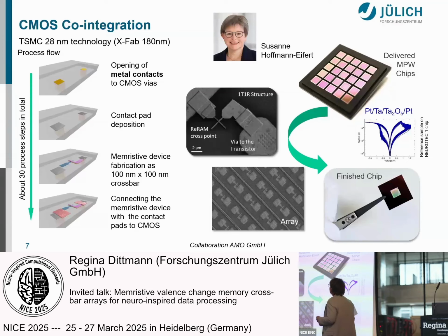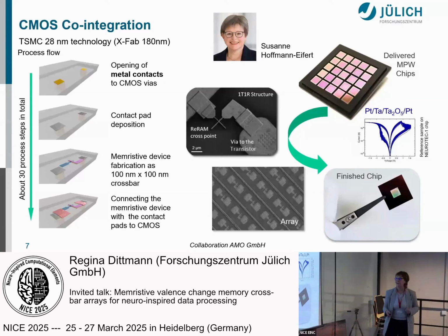In particular, this was quite complex for the TSMC 28 nanometer technology because it goes along with copper. This causes a lot of problems or challenges in our institute. But we finally managed to do this and now have these nice memristive devices on top of the CMOS chips, as you can see here.